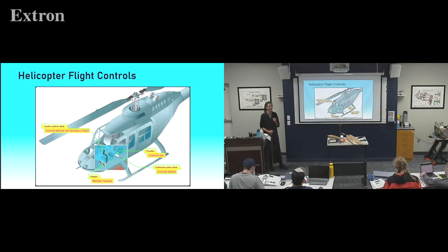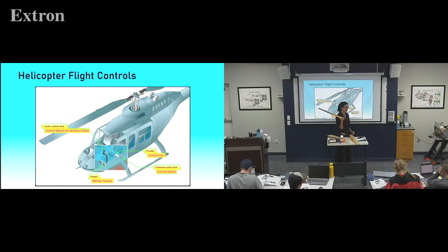Question. Do the anti-torque pedals control the pitch or the speed of the tail rotor? It's just the pitch of the blades. It's a set speed, but it's connected to the engine directly. It's all geared to the main rotor.